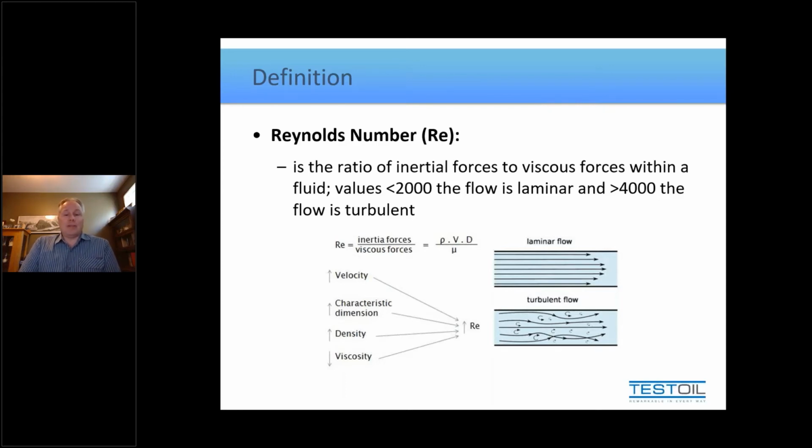So as you can see, we have a standard that doesn't purport to provide very clean oil, and we've got another standard that doesn't really give us a good foot to start off from during commissioning. So knowing we have these things working against us, or certainly not with us, we have to come to this understanding: well, just how clean should it be, right? We're kind of on our own here, so we need to go with our own mentality and decision making and decide how clean is clean enough for our system. What I always like to point out is there's no point knowing how clean it should be if you don't know how clean you're starting with.